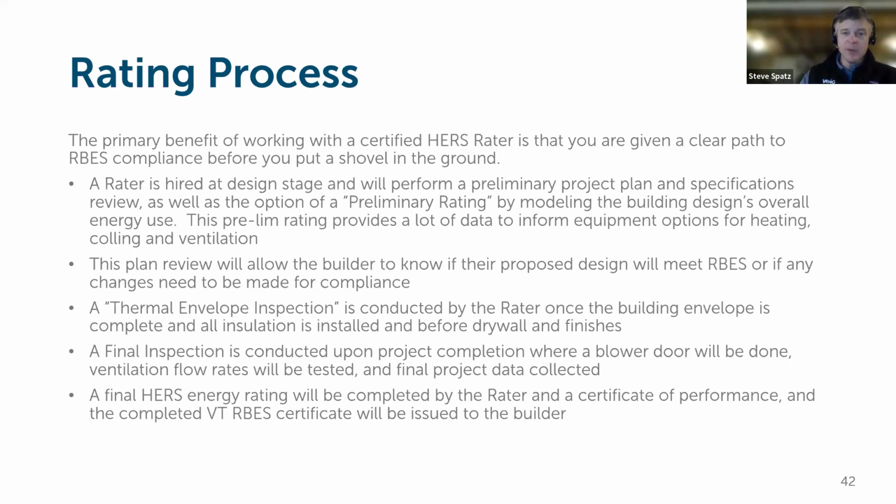That shows where this design, as it stands right now, lands in relation to what the code is requiring for compliance. So this is a great way to guide the construction process. The RBES check tool is a similar approach, where you can enter your proposed components into the tool, model out how they compare to what the code would require, and then make any changes or adjustments before you start putting the building together on the ground to get you towards code compliance.